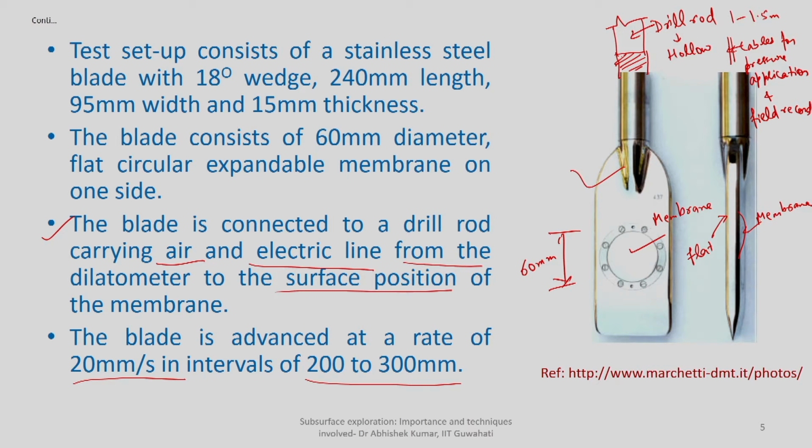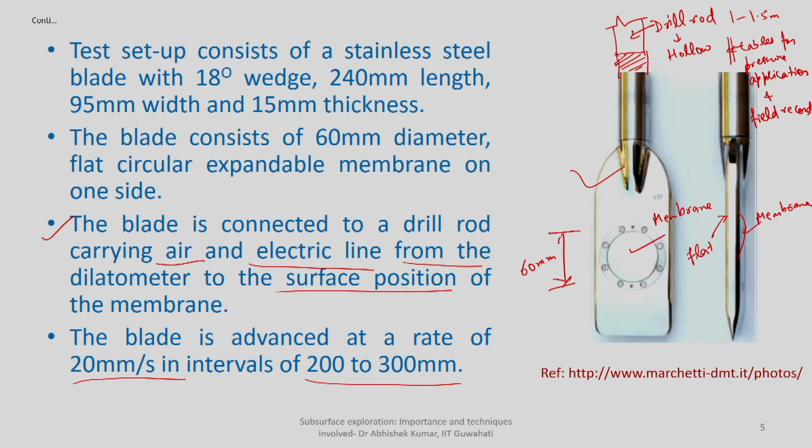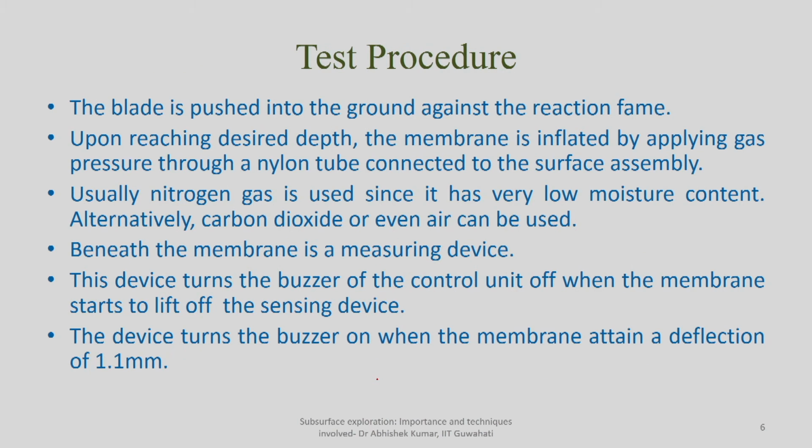You keep on repeating the same test procedure up till you reach the desired depth of exploration. So very much similar to your CPT test, even the dilatometer test also gives you continuous recording. Continuous in the sense, at an interval of 200 to 300 mm, you will get different values. Okay, so the test procedure, in the last slide I showed you the blade, which consists of a membrane.